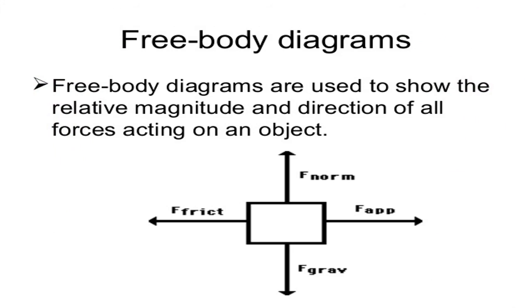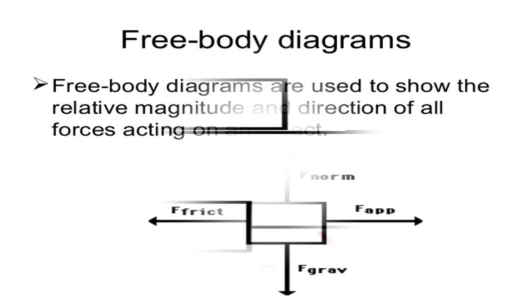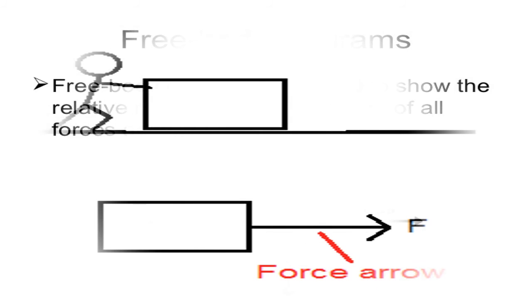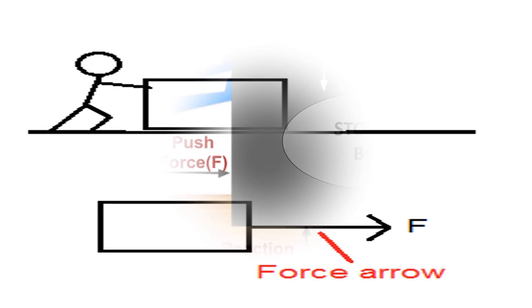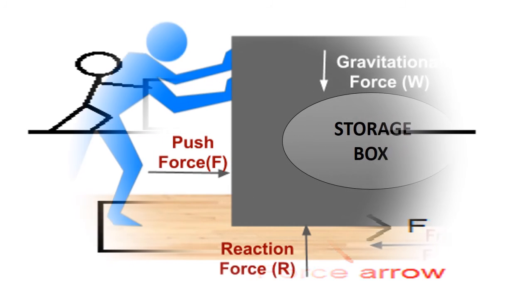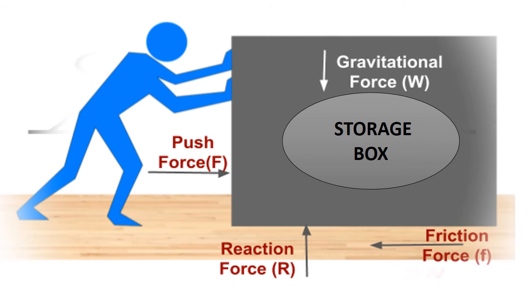A free body diagram is not a scaled drawing, it is a diagram. The symbols used in a free body diagram depend upon how a body is modeled. Free body diagrams consist of a simplified version of a body, often a dot or a box. Forces are shown as straight arrows pointing in the direction they act on the body. Moments are shown as curves with an arrowhead or a vector with two arrowheads pointing in the direction they act on the body. One or more reference coordinate systems are also included.